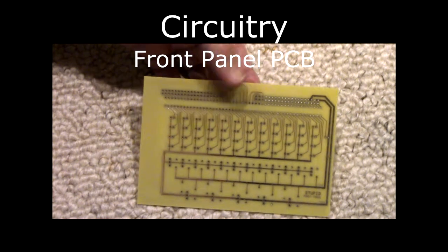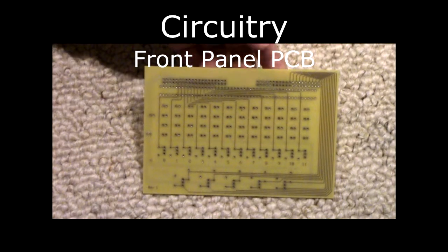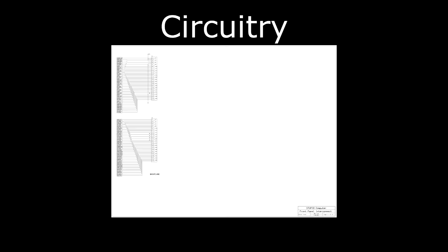Now, this is a double-sided board, which contains only the LEDs, the switches, resistors, maybe a capacitor, and the connectors, which will take the signals off to the main circuit boards. So the circuitry that actually drives the LEDs and debounces the switches is in the main computer. The connection between them, I'm using two IDE cables, which are cheap and readily available. I need two because each one is 40 lines, and I need more than 40.